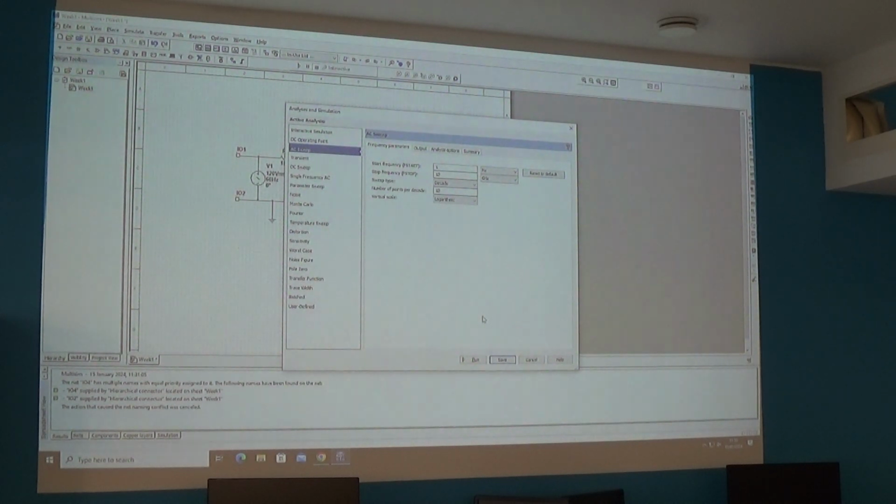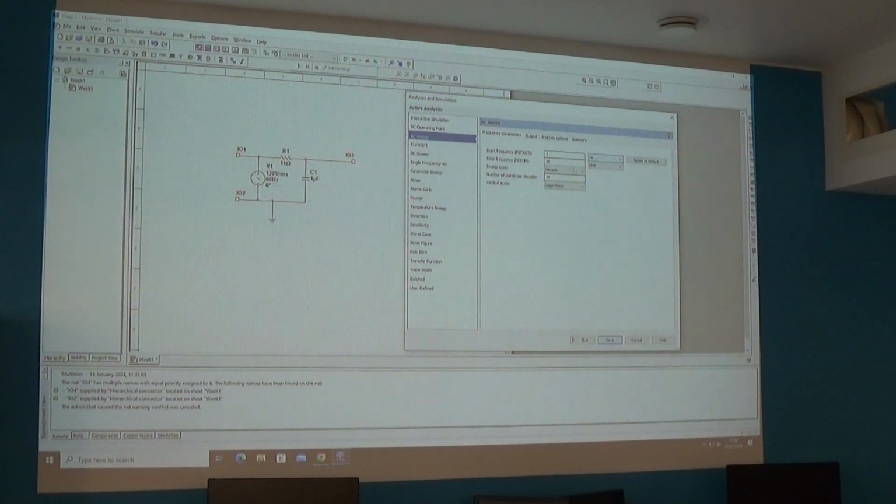and you'll see on the right hand side there we've now got a series of options. Now I happen to know, only through experience, that a start frequency of 1 Hertz is fine. So 1 cycle a second, I can live with that. But do I really need to take a circuit with 1K and 1 microfarad up to 10 gigahertz? Probably not. 10 gigahertz is a pretty high frequency. So I think what I'm going to do there is I'm just going to click on the megahertz for the time being, and I'm going to go from 1 Hertz to 1 megahertz.